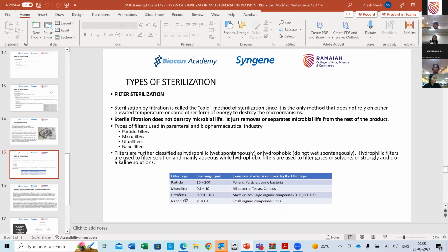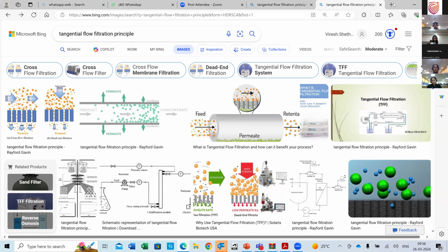So imagine a tube in tube kind of a situation. So you will have one tube in which there will be an external tube which will be used for housing the internal tube. The internal tube is where your membrane is sitting, and the membrane has the hole or multiples of holes which are there. Again, let me see if I can get a picture of hollow fiber membrane for you.